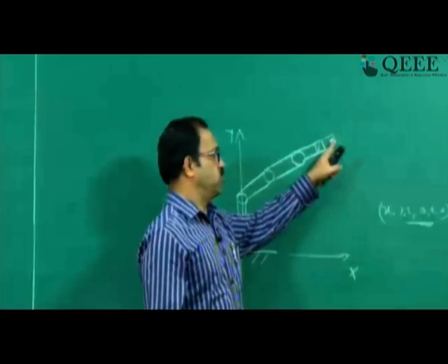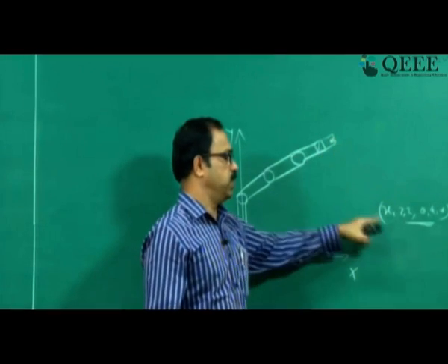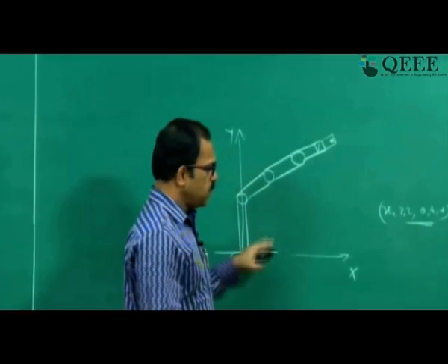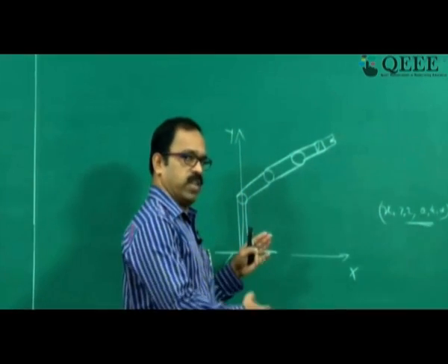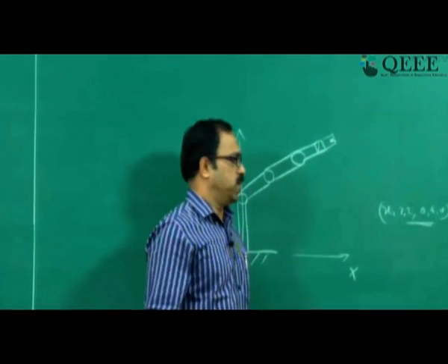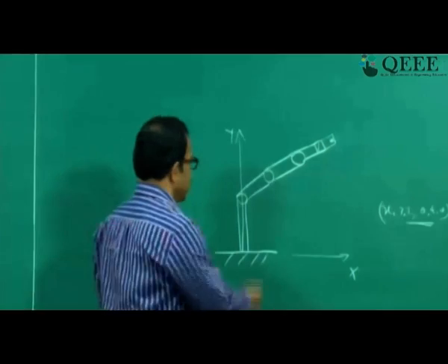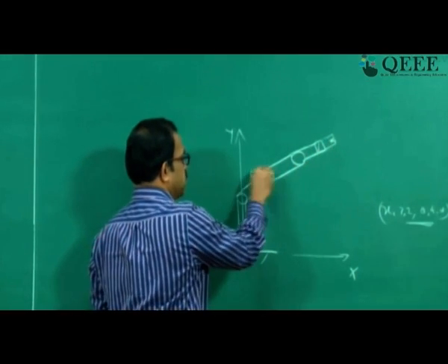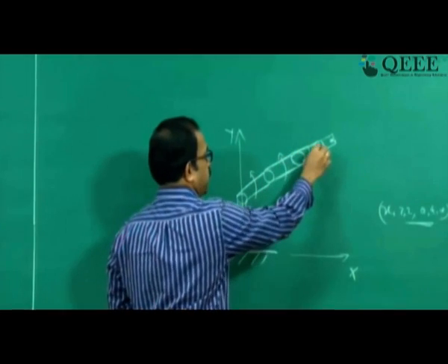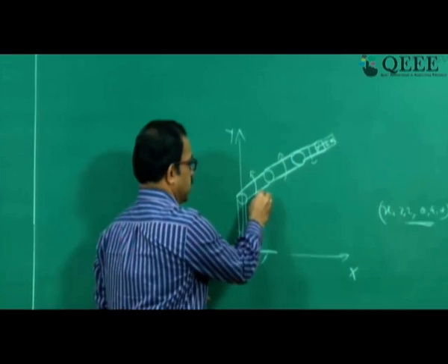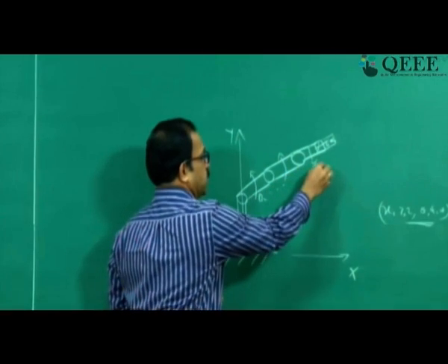In the Cartesian space, the position will be given in terms of x, y, z and the roll, pitch and yaw angles, or we can have the normal, sliding and approach vectors for the orientation part. This can be achieved by changing the joint parameters which are the variables, theta 1, theta 2, up to theta n.